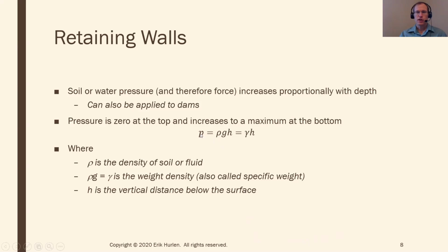The amount of pressure is proportional to depth, called H, and also proportional to the density of the fluid and then gravity. So density times gravity times depth gives you what's called the hydrostatic pressure. Again, that's proportional to how deep you are. If H is 0, right at the very top, it's 0 pressure. Then the deeper you go, the bigger the value of H, the more pressure you feel. It also depends on the density of the fluid. Obviously, if you go underwater, you're going to have a lot more pressure than under air because water weighs a lot more. It's a lot more dense.